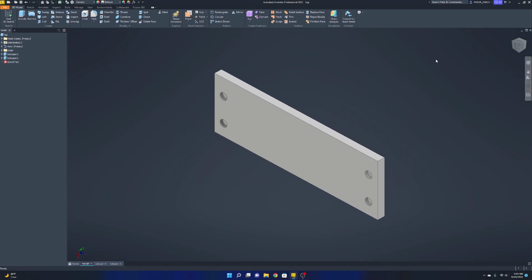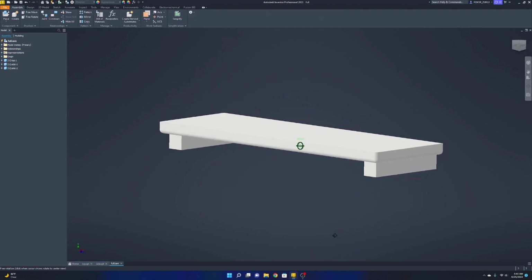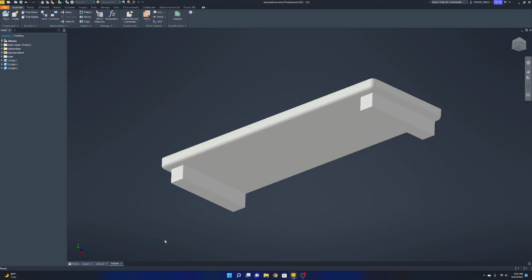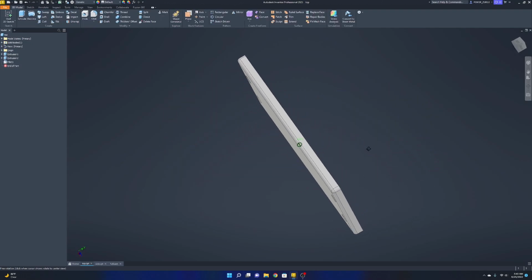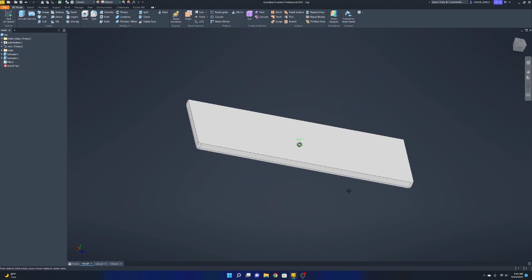And I'm going to click on this fillet button right here, and I'm going to select all these bottom edges, and I'm going to write 0.5, and what it's going to do is curve it up, but I'm also going to select these 2 edges right here. I'm going to press OK, and we can go back here, and now you can see that we have a little bit of a curve, smoothing out our edges.